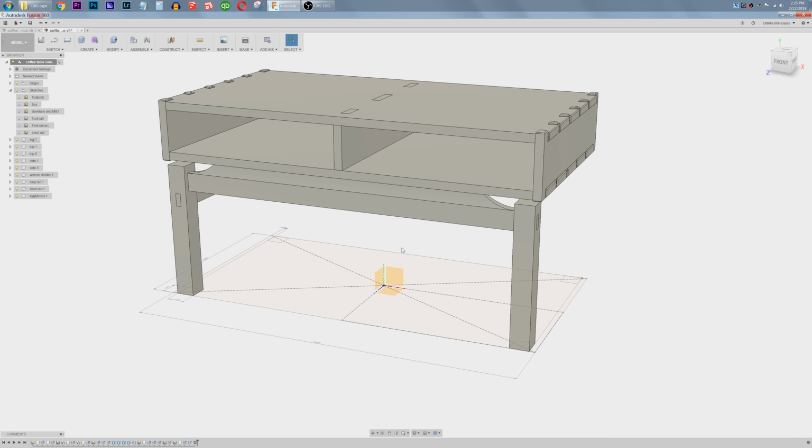I wish that mirroring worked just the way you copy and flip in SketchUp. If you copy a component and then flip it in SketchUp, then that is essentially making a mirror, and that maintains all of the features of that. I wish that there was either a flip command or a mirror that kept those relationships, but it simply doesn't. So that being said, I need to back up my history, and I need to make all of the adjustments to the leg before I mirror it.